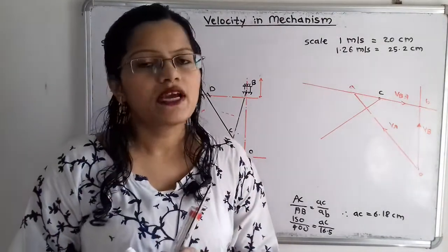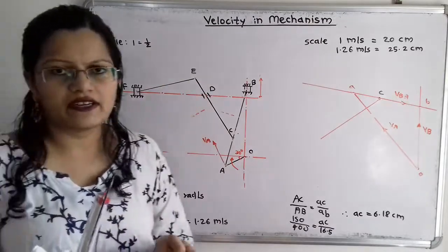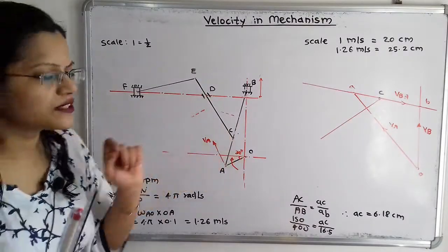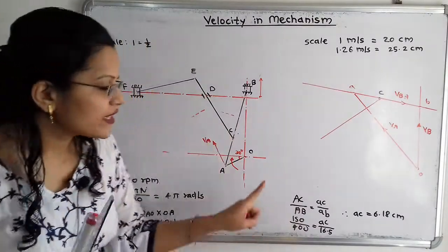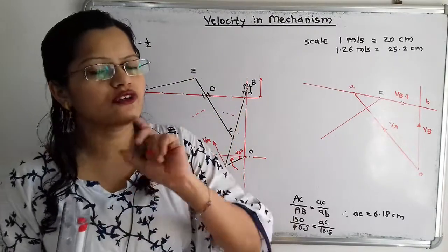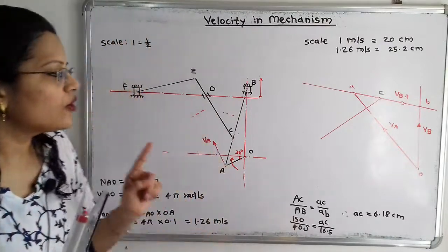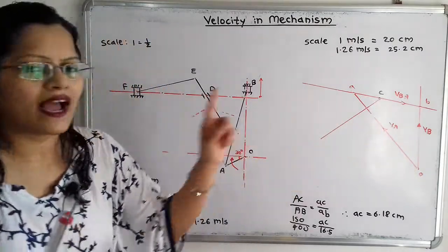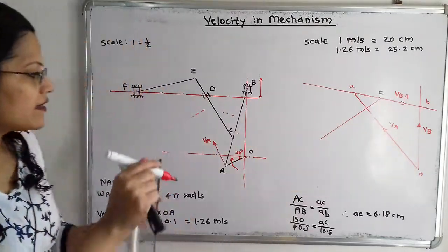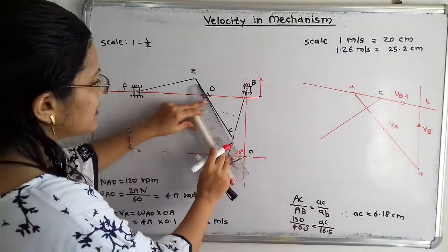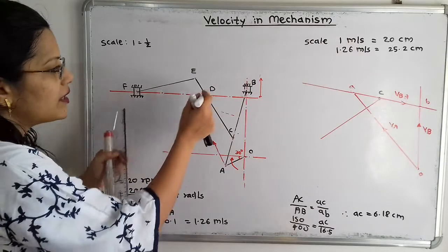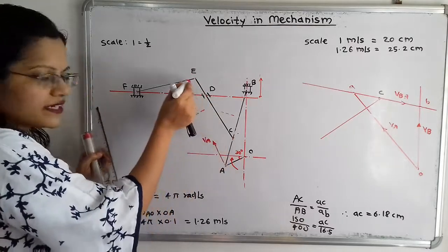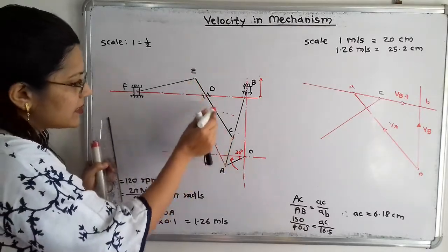So this is an important point, because at point D there is the trunnion, and in the trunnion there is the reciprocating motion for this link CD with respect to O. So with respect to the fixed point we have to show the reciprocating or oscillating motion. So remember that. When I draw a line parallel to this CD but passing through this point O, I will get the point D. So here I will take one line parallel to this link CD, because this is the motion. At this point, this link CD will oscillate along this link CE, or along this direction.